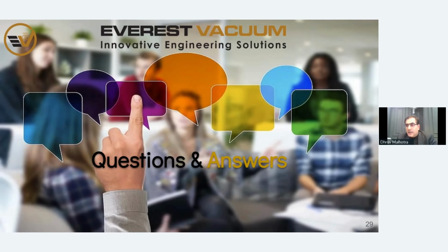The disadvantage being that in case the source of feed is not proper and you have very heavy carbon carryover, it will cause choking or jamming in the dry screw vacuum pump. It will require more cleaning as compared to that required in an oil seal. But if you are very sure about your quality of feed and you're disciplined in that, dry screw is a great choice.